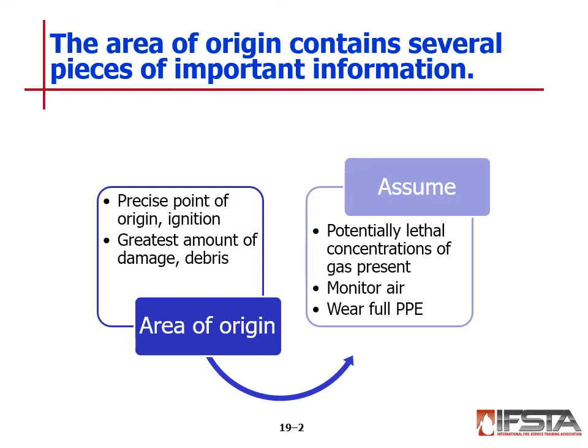So this is where you're going to see a lot of the damage to the structure itself. Maybe sheetrock is missing, or in other areas of the house it isn't. You'll see very deep alligatoring on support members, wood.